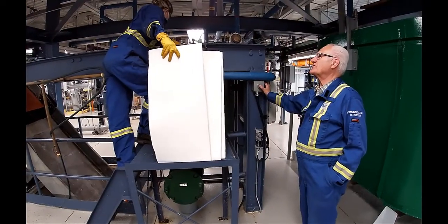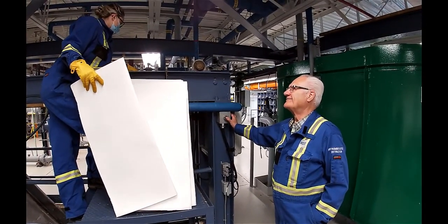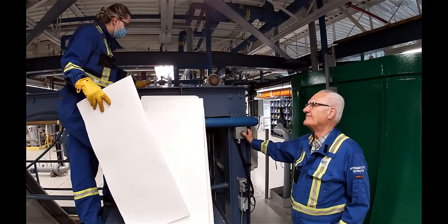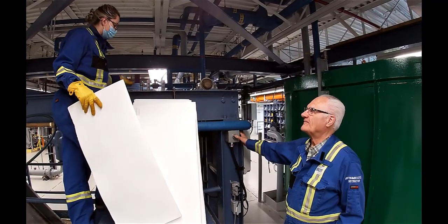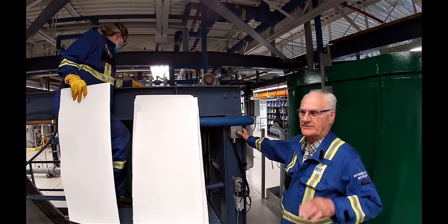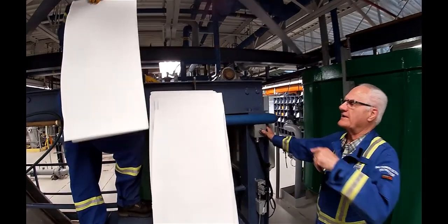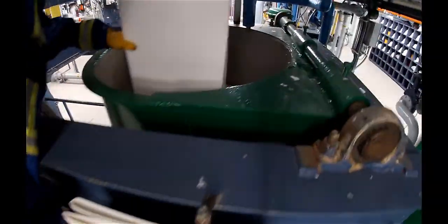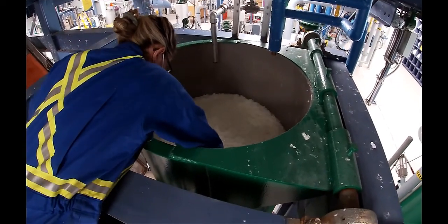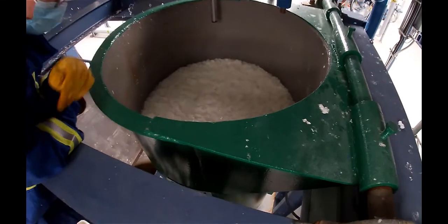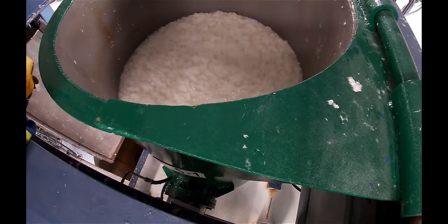So, Mari, how much time are you allowing between the sheets now? Probably 20 seconds, and I can see the surface slowing down through its circulation with the agitator. And then it speeds up once the sheet has gone through. Good. So now you've got an idea of what you've got to look for. Ray, if you can just get a shot of that right now, you've still got another 10 sheets or so, but you can see the one that she's putting in right now. She really has to give it a push down to get it into the actual slurry itself, and then she's waiting to see it circulate through the agitator and come back up the other side.